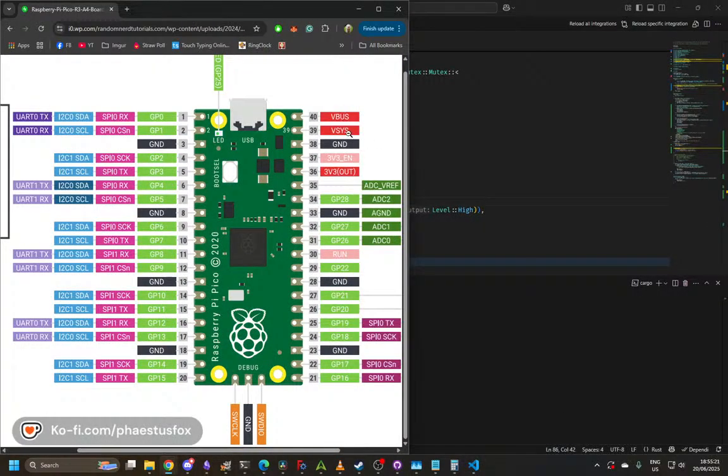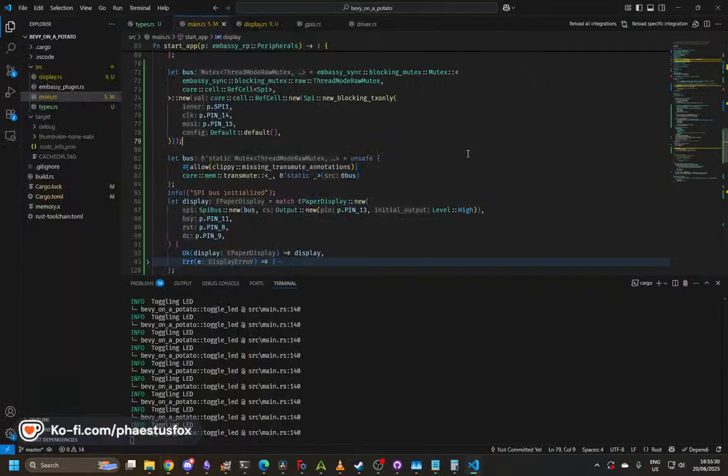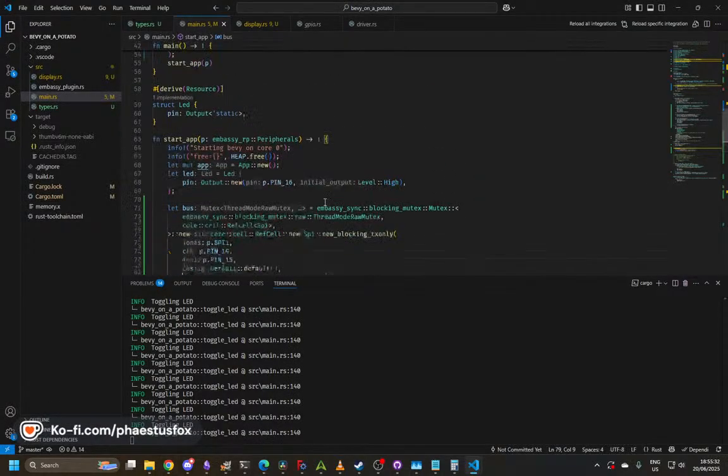Anyway, there's VBus and VSys, and I don't remember which one's which, but one of them has a diode connecting it to the rectifier, whereas the other one connects directly to the rectifier, which means that if you plug into one or the other, you get better efficiency. So we'll work that out later when we get to that point.